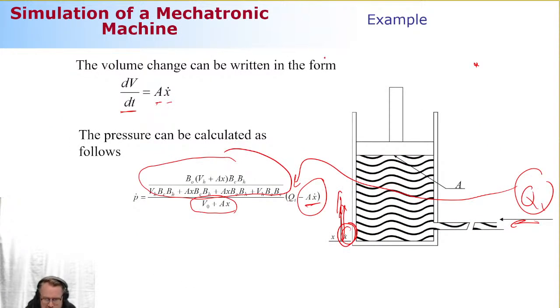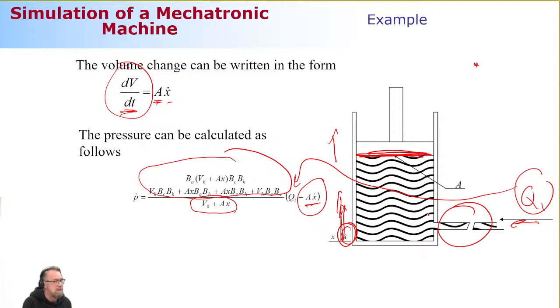Then it continues. The last component that defines whether the p dot is positive or negative is the change of the volume itself. Change of the volume is something that you need to consider carefully, because it actually comes from the cross section of the piston multiplied by velocity. Now if velocity is in this direction, the positive velocity direction, it is taking the flow rate off from this particular area because it's sucking the flow, sucking the material off. And that's why it's going to be negative here.